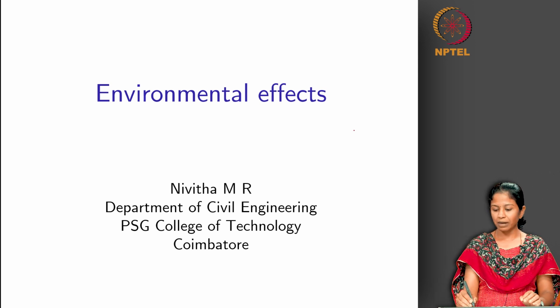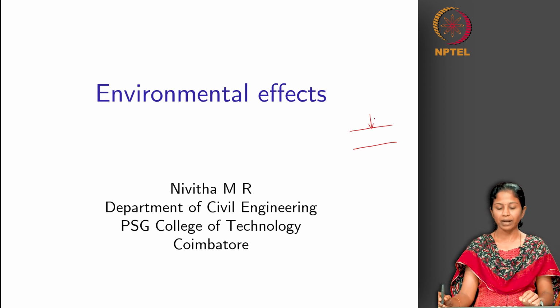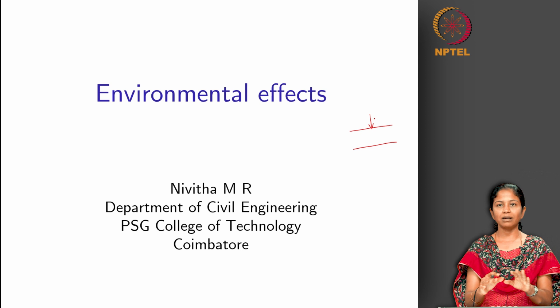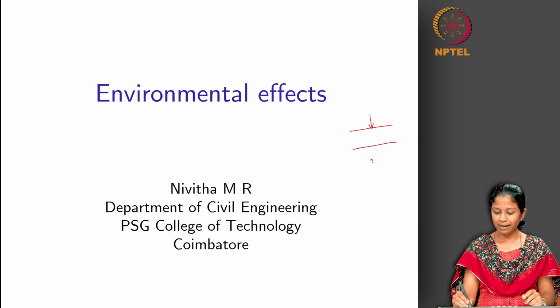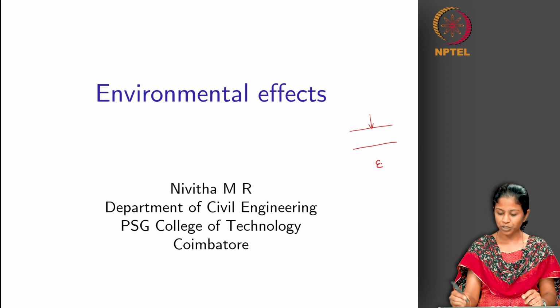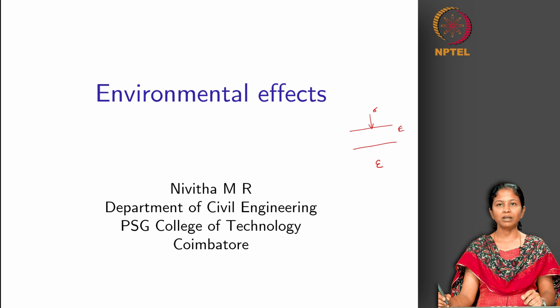If we take a typical pavement, right, the load that we experience from the vehicle is going to remain a constant, right. Let us say that it is a typical loading scenario we experience in a pavement. So now the amount of strain that we get for a given stress is going to ultimately depend on the modulus value.